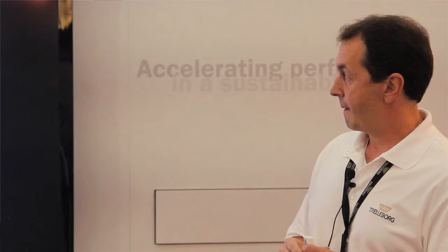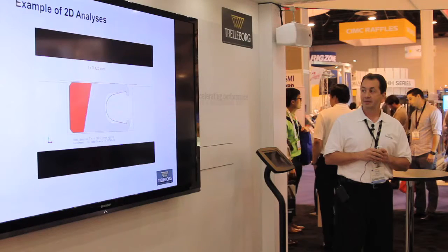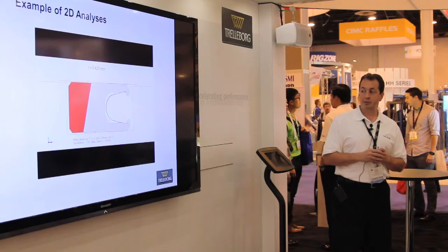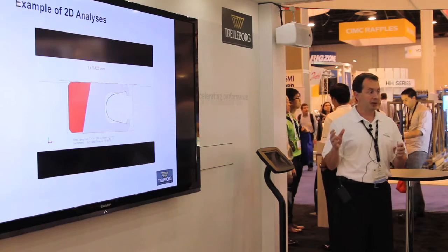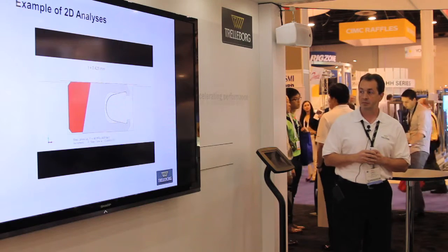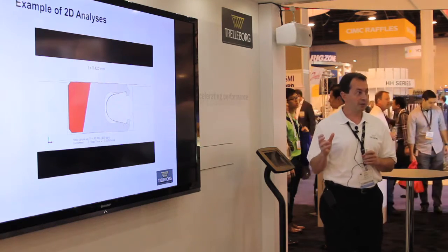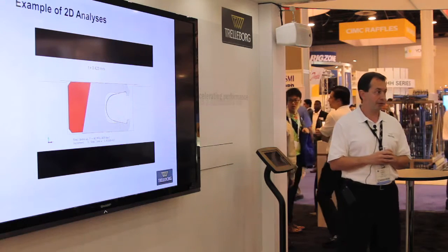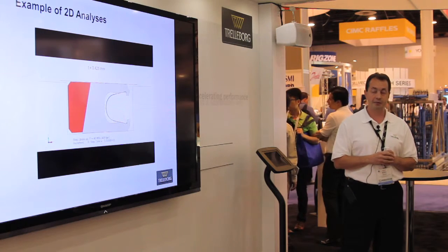So the next step here is to apply temperature to the seal. And we'll give it 1 second to load. As you can see, now the temperature is being applied to the seal. You can see the materials expanding. We'd use this to check for volume fill to make sure that when the seal is heated, it does not overfill or over-occupy the groove.